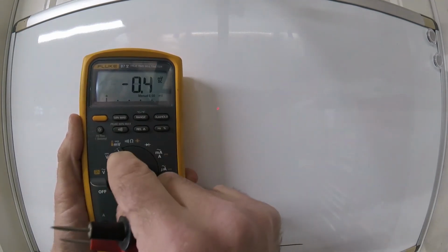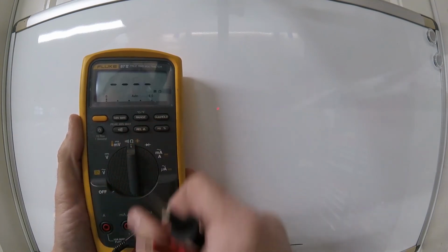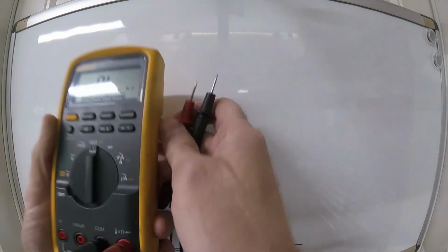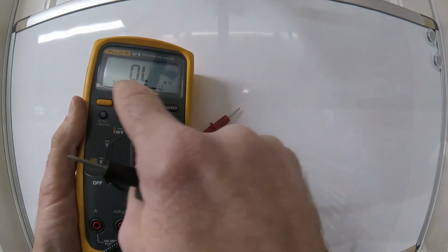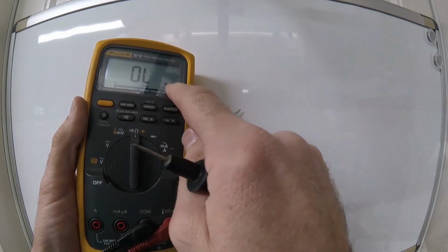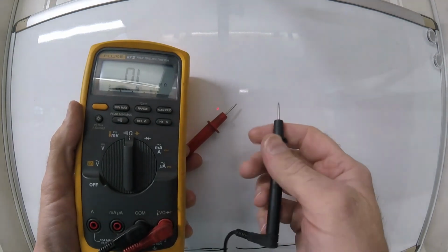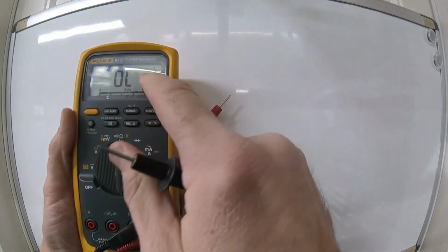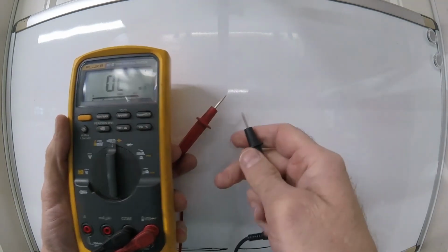Here's a scale for reading millivolts. That's really tiny voltages. Here's a scale for reading resistance. You see the omega for ohms. And right now, when a digital meter like this reads OL, that's overload, and you see the M over here next to the ohms, that means that the resistance is so great that it can't measure it. So that's infinity, or just too many ohms.